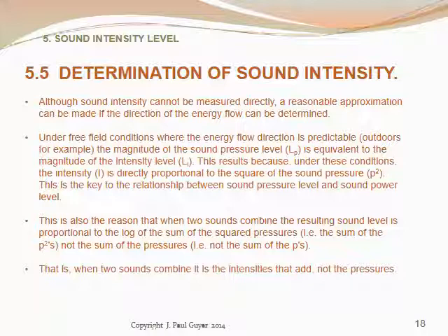Recent advances in measurement and computational techniques have resulted in equipment that determines sound intensity directly, both magnitude and direction. Using this instrumentation, sound intensity measurements can be conducted in more complicated environments where free field conditions do not exist and the relationship between intensity and pressure is not as direct.